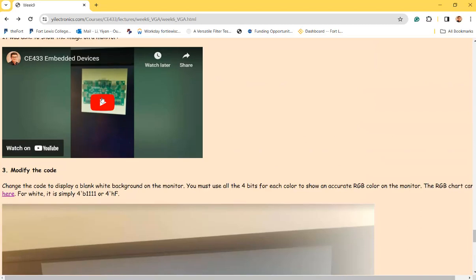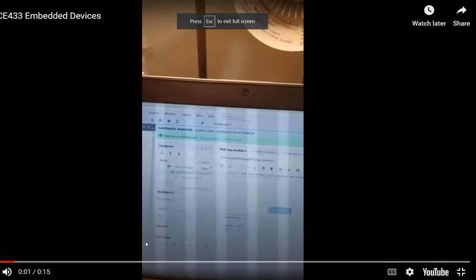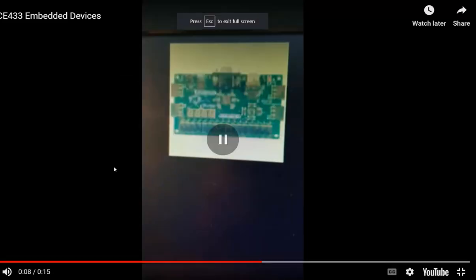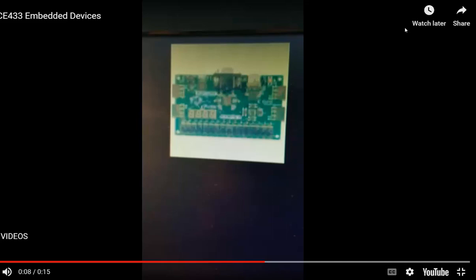But for this one, this is a basys 3 picture, the board picture. You can see the board should be blue, right? It looks like something in between blue and green, because you only have 3 bits for R and G and 2 bits for B. So B is not being represented really well. I only have 2 bits, which is four different levels for B, which makes sense. So this will be a little picture being displayed onto your monitor as one of the demonstrations.